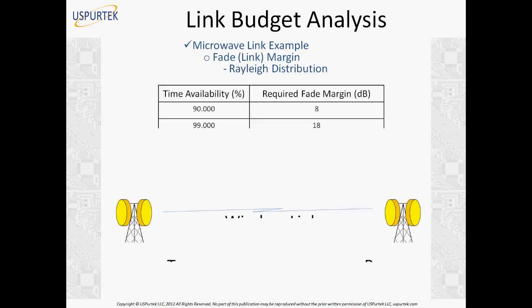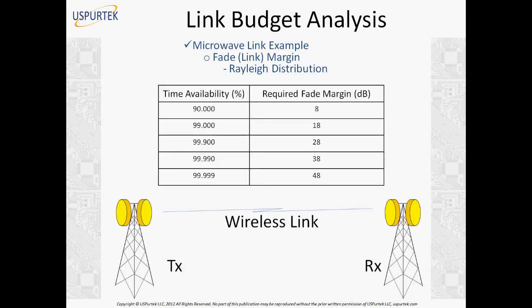So this is a very general Rayleigh distribution which can be used to estimate the required fade margin. Fading effects change with location, and they could change with time also. Even if you are at the same location, the atmosphere or something else will change and the signal will fade. Signal level does not remain the same throughout the life of the equipment. It will change from time to time based on environmental effects, and if you are mobile, based on your location inside or outside the building.